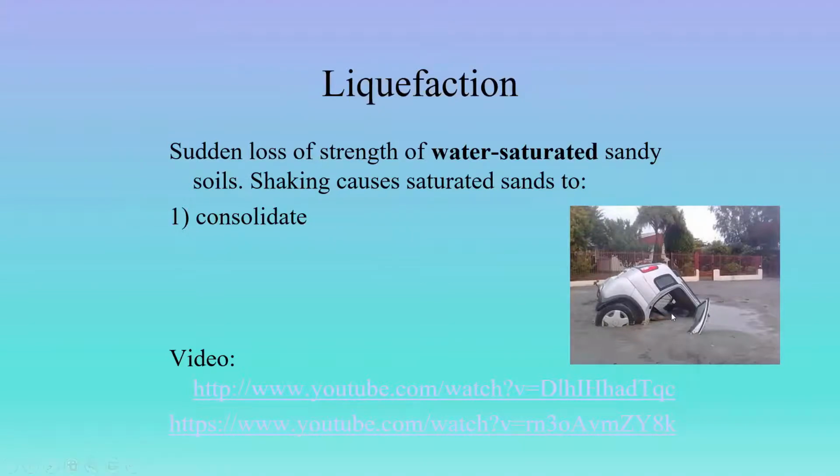So the ground literally liquefies under your car or your vehicle or whatever, and then your vehicle sinks into it. But when the shaking stops, it's like taking a bag of cereal and shaking it: it's eventually going to compact down to its lowest volume, or consolidate.